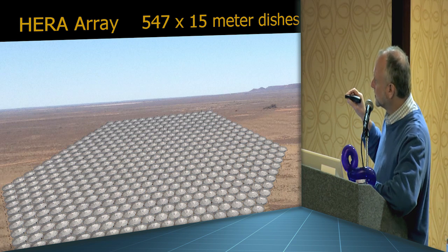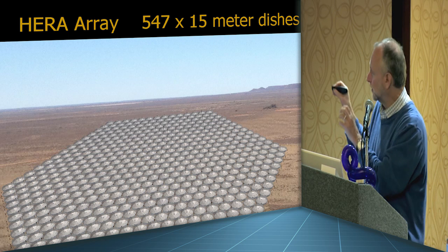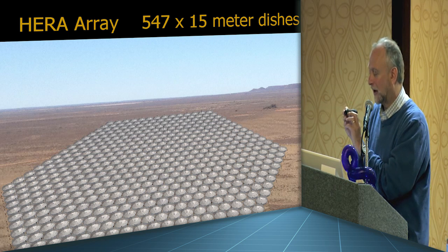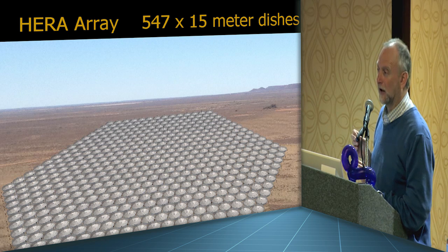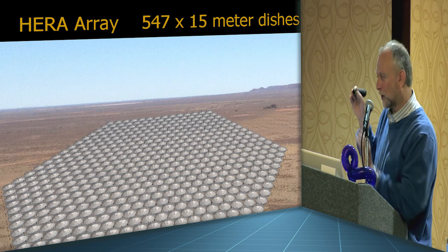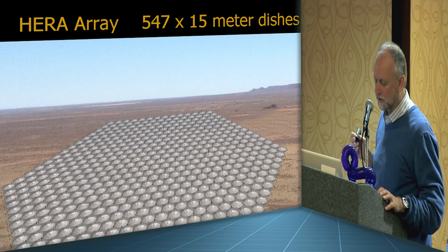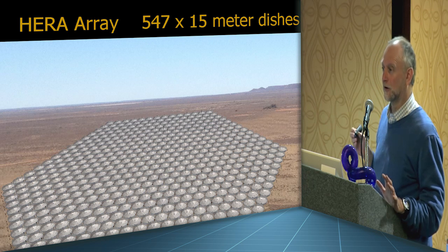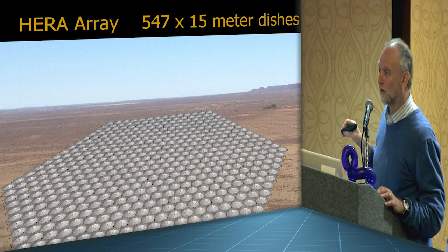What we're thinking is we're going to maybe take a little cluster of three or 4, or maybe 8 antennas, and have a little station there where we digitize the data locally at that little batch of antennas, and get the data into Ethernet, maybe 10 or 40 gigabit Ethernet. Then at that station we will transmit the data on different colored lasers, CWDM or DWDM, we're not quite sure which, to minimize the number of fibers.